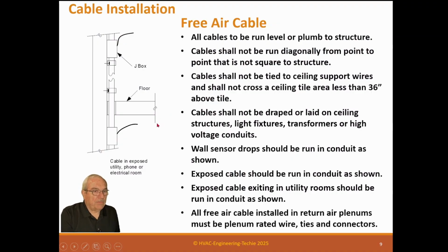All free air cable installed in return air plenums must be plenum-rated wire, plenum-rated ties, and plenum-rated connectors. That's really important. You don't want to make that mistake of using standard ties or standard wire, and an inspector finds out that it's not plenum-rated, you'll have to change it all. There's no other reason. It's no big deal. Just make sure you have that.